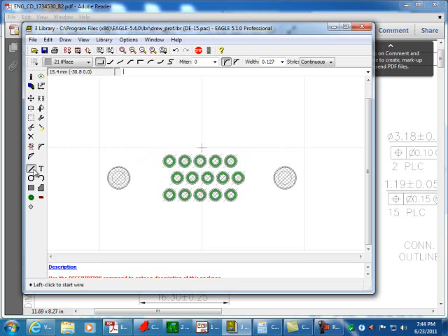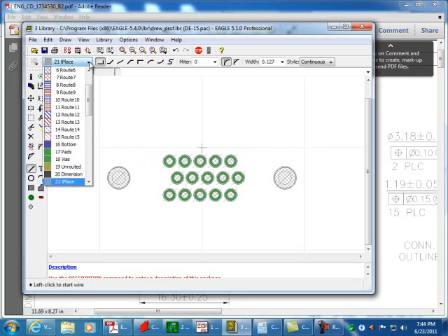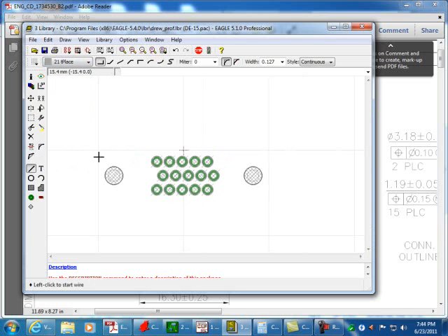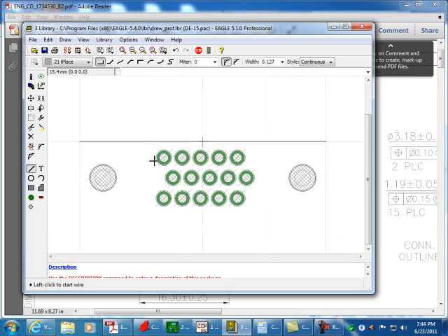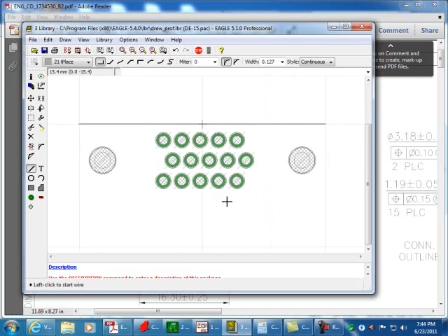So I'm going to create a line, and by default it's already selected. We're going to use T-place, top placement, and that's what you should do your outlines. So from negative 15.4 to positive 15.4, and then hit escape. That covers the back edge of our connector.